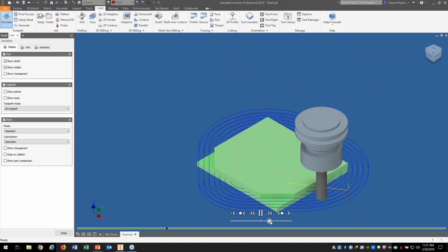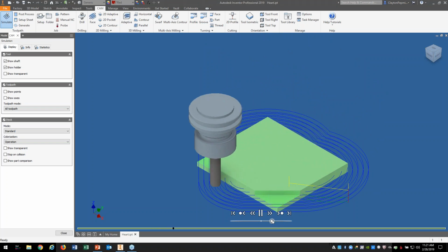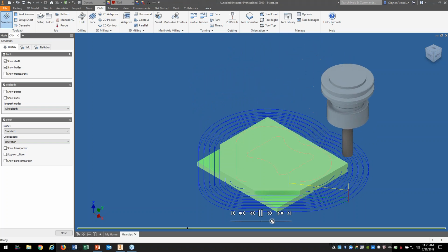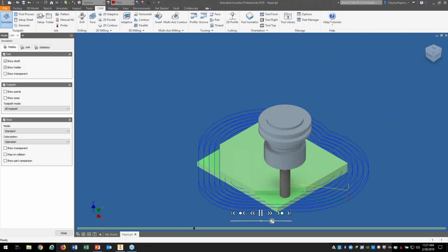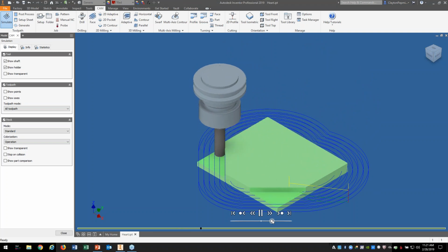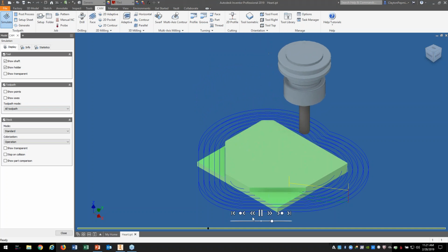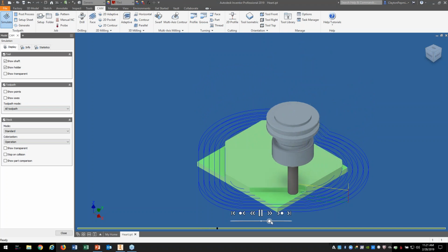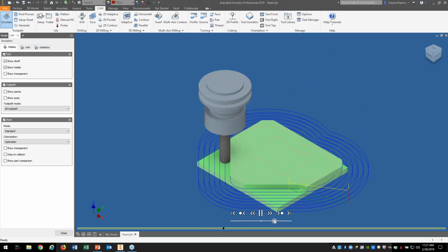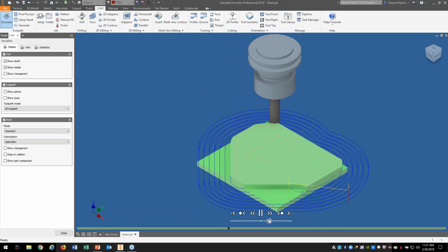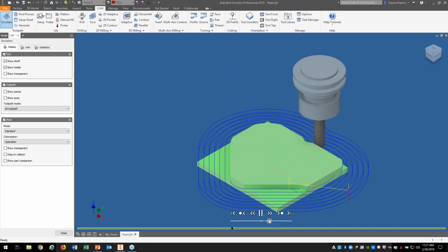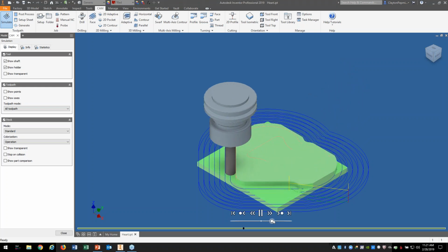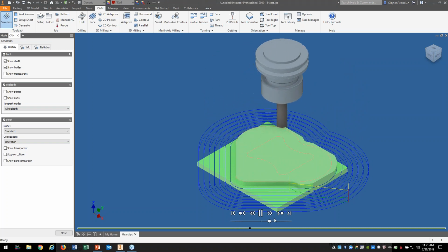But as I was speeding it up and slowing it down, trying to eliminate all that air time that's being run, my boss just had a fit every time he'd walk by the machine and see this tool out there cutting all that air. But with conventional machining, that's about the only choice you have. You almost have to do a little air cut because it's following the shape of the part. So I would stand there at the control, speed it up, slow it down. And the ones that would get me in trouble, right about here, I'd speed it up and forget that it's taking a little dip there, and I'd end up damaging my cutter. Again, all the drawbacks of trying to manipulate the controller.